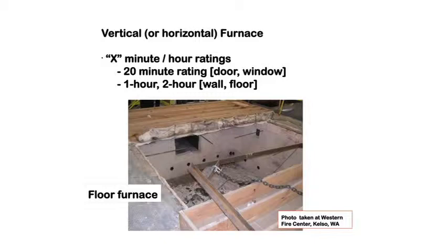So this doesn't apply directly to wildfire situations, but many people are adopting 1 hour wall construction for exterior walls for wildfire situations. So if you have so-called one-hour wall construction for your house, you would have the siding on the outside, and then somewhere between the siding and your stud wall, you're going to have gypsum wallboard in that assembly. So even though it doesn't apply directly, it is used in defining acceptable products or assemblies for wildfire exposures.